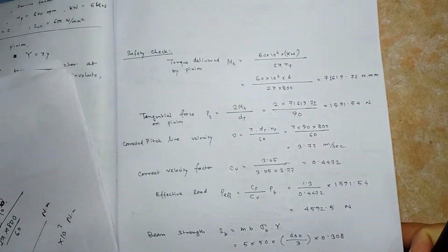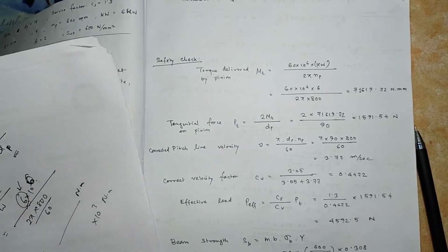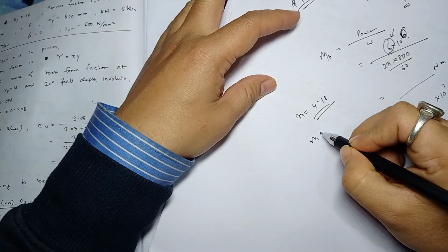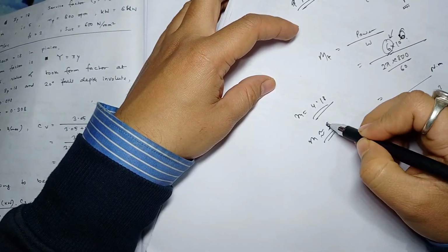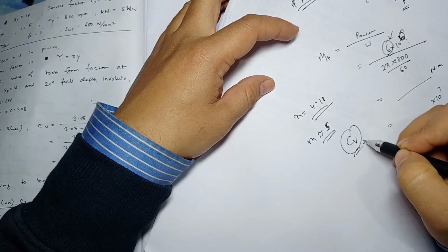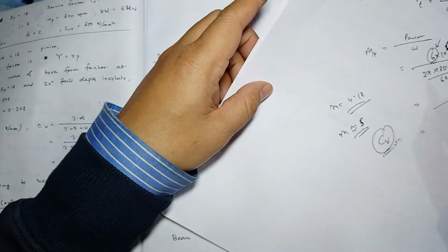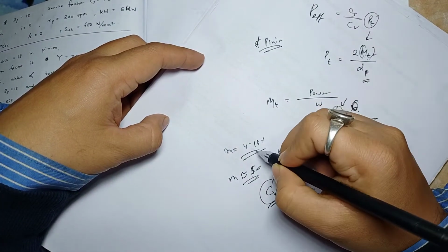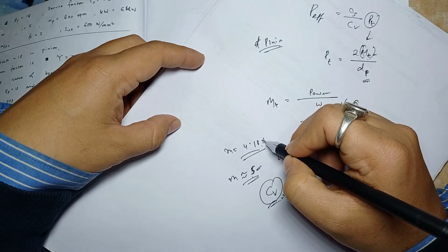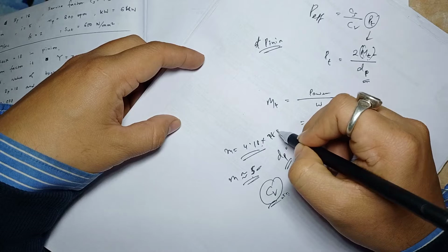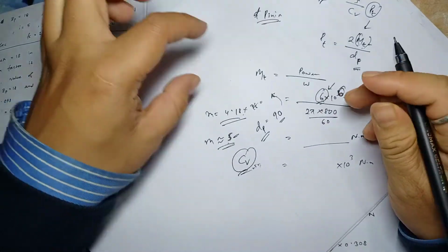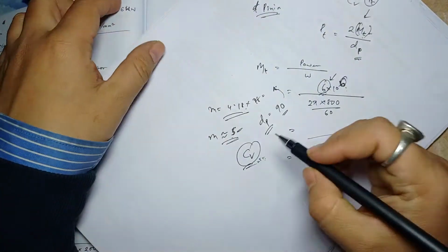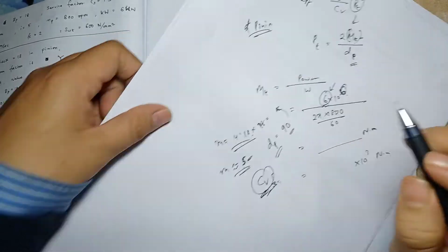Now the pitch line velocity has to be corrected, because the calculated value of module is 4.18, but you have estimated it and taken it as 5. So this factor Cv has to change in this case. Using this module you have calculated the diameter as 90, otherwise it would have been module multiplied by z, which is 18, so less than 90. But you have increased the diameter, so your velocity will change in that case. That's why you have to correct the velocity factor, Cv.